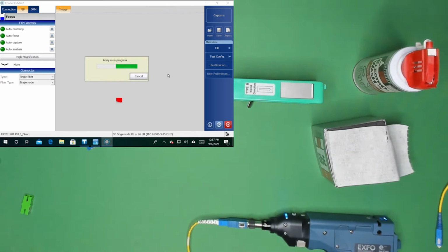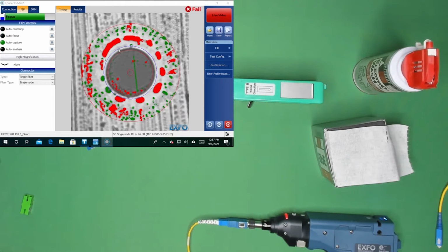And we're losing a little bit of resolution going across VNC here. But essentially, obviously, we have a bit of a train wreck here. If I double click on it, you can kind of see. Anytime you see this rounding, almost like this cratery effect of debris, how it pushes itself out, this is the contact zone. You can see how all the oils push themselves out to the end. This means that there's cross-contamination. It's been plugged in dirty.